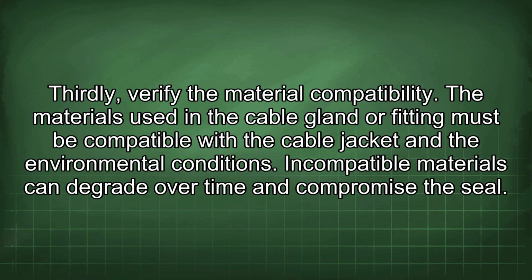Thirdly, verify the material compatibility. The materials used in the cable gland or fitting must be compatible with the cable jacket and the environmental conditions. Incompatible materials can degrade over time and compromise the seal.